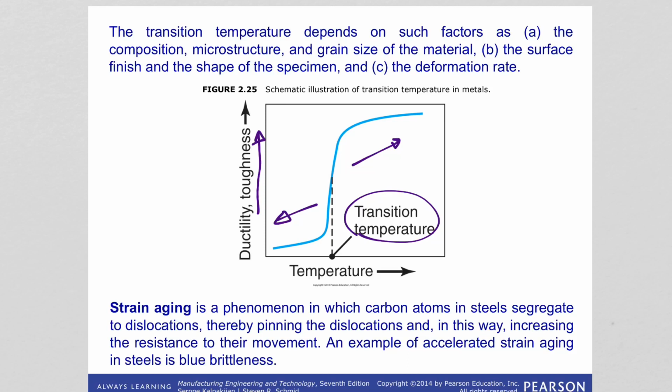So this is why the Titanic actually failed, because they were going through very cold temperatures, and normally the ductile steel they made all the ship from, right? Normally the ductile steel, under cold temperatures, became brittle, and when they hit the iceberg, since it's a brittle material, it acted as a brittle material, it cracked and the Titanic sank. So that's why this is important.